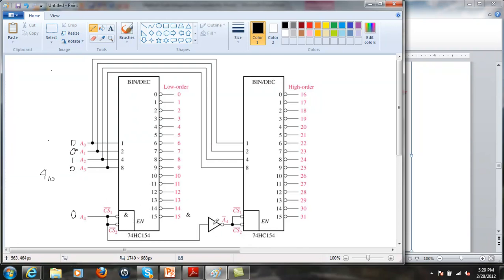This chip is inverted, so this one, I'm actually going in with a 1 here. So this is disabled. This isn't working. And therefore this 1 that translates over to here does not do anything. It doesn't activate the 4th pin down, whereas it does activate the 4th pin down here. So for this particular one, this would be a low, and the rest of these would be high, since this is an active low output.